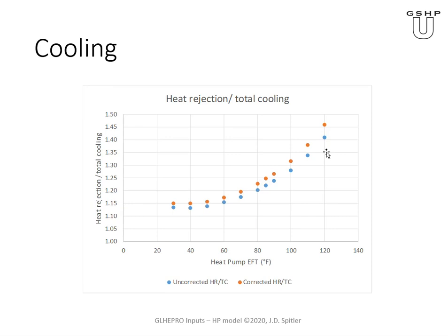to provide cooling with. So I would be surprised, at least in this part of the country, if we design the system with design temperatures much above 90 Fahrenheit. So probably we're more in this range, but you can see the difference between here and here is maybe 3% or so.